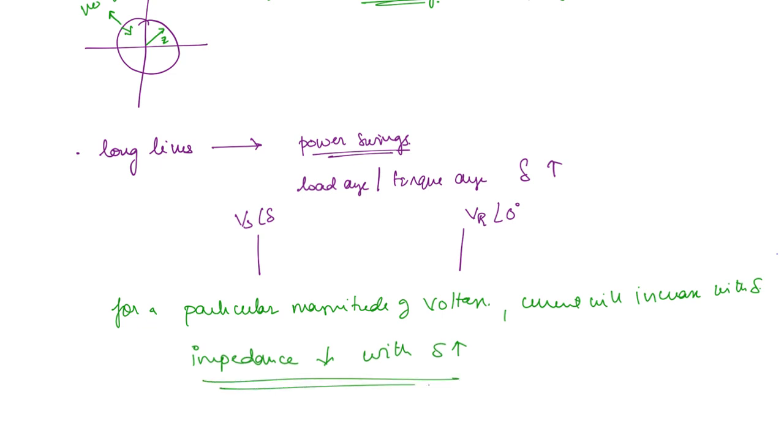So this is the important point here. In case of power swings, changes in the power, the delta will change and so impedance will change. Once impedance changes, it is also going to affect the operation of the impedance relay, right? So for this reason, the mho relay is preferred because it is less sensitive to this kind of power swings.